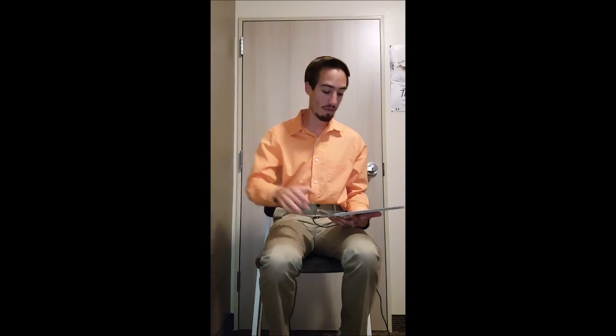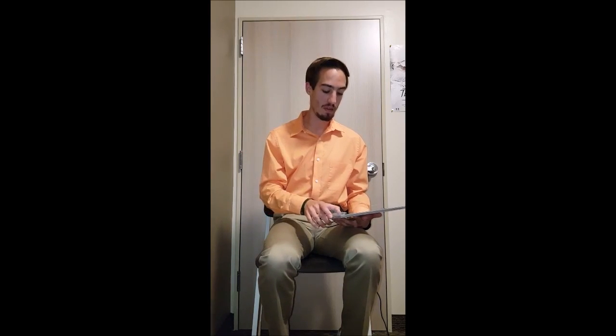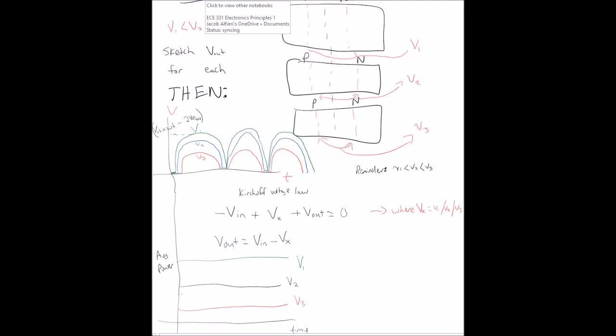Consider if the diodes from the full wave rectifier have different voltage drops: the output voltage over the load of the RC circuit changes. By applying Kirchhoff's voltage law, you find that a smaller voltage drop over the diode equals a larger voltage drop over the output. Because of this, you can also consider the power of the RC circuit, where if you have a smaller voltage over the diode, you will have a larger power dissipation over the load.